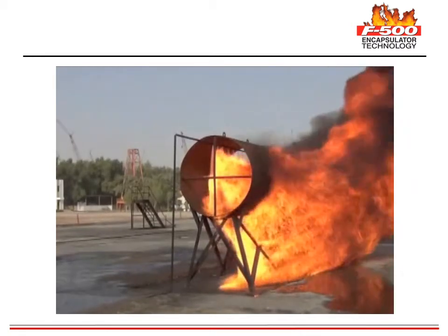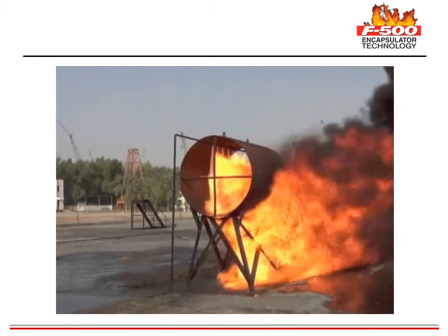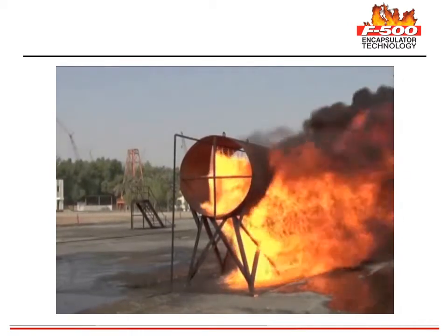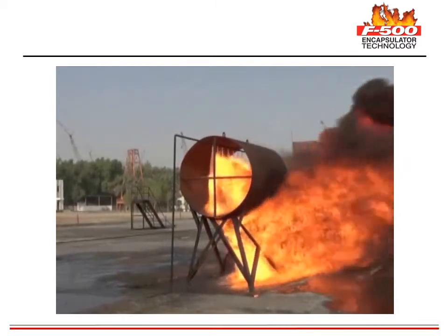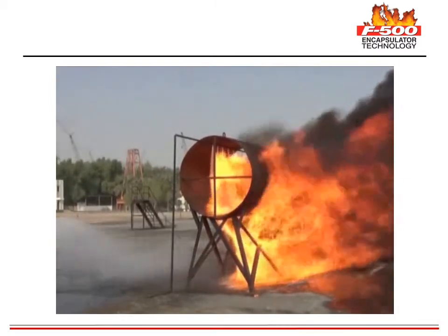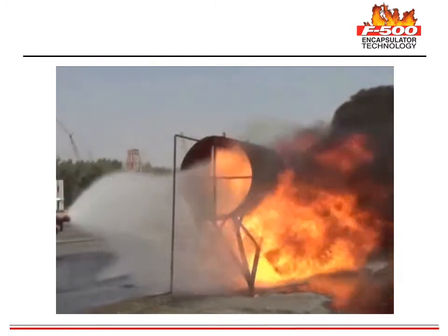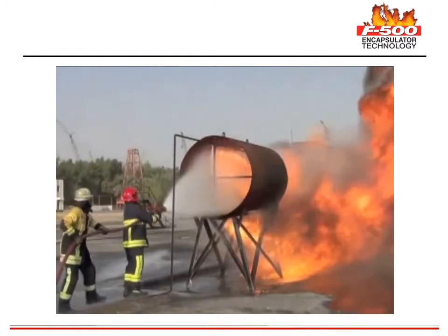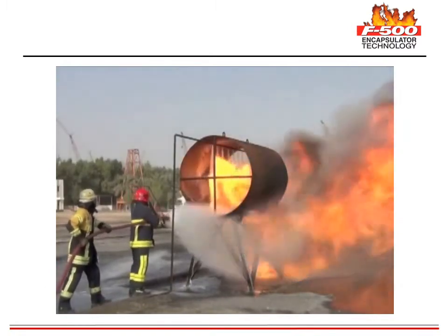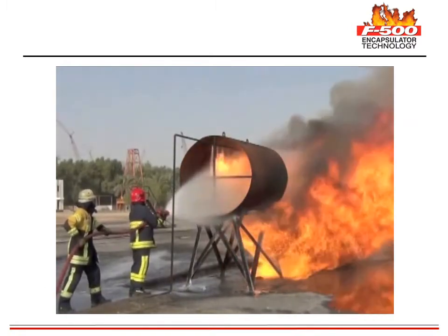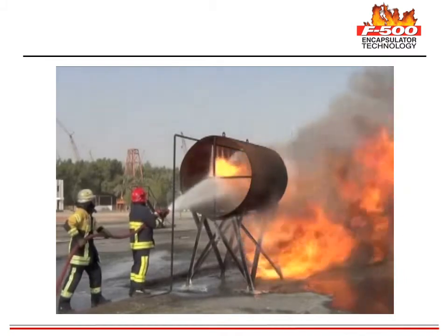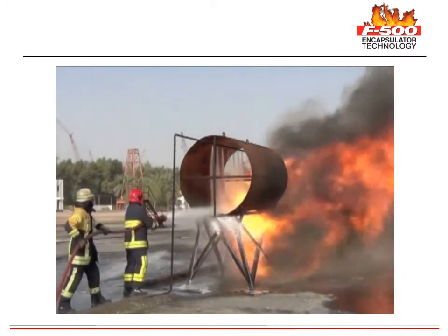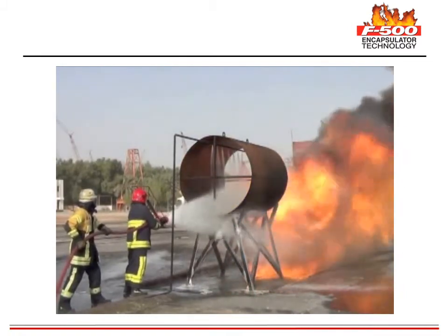This video captured a training exercise in Dubai, United Arab Emirates, simulating a three-dimensional fire on a jet engine cowling. After the jet fuel was ignited, a mixture of salt water and 3% F500 at 87 psi is used to attack the fire. The firefighters use a 1.5-inch handline, 95 gallon per minute nozzle, and eductor. The fire was extinguished in 23 seconds. Foam cannot fight this type of fire.